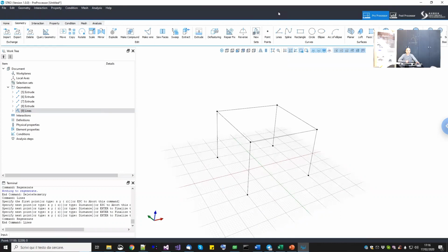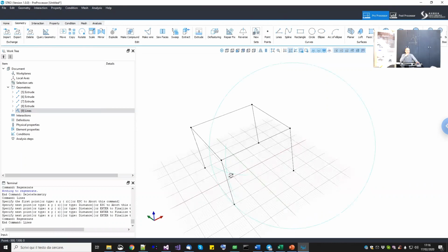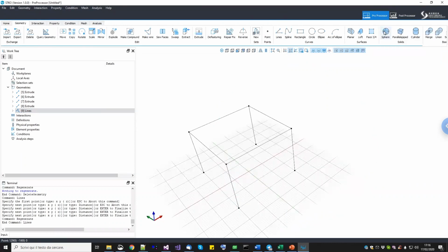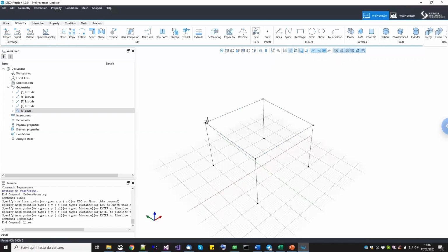Okay, sorry. Perfect. As I told you, in this example we are going to model everything in continuity. Later on, we will add discontinuity at the nodes to create the beam column joints. So if I want to merge all these geometries into a single one, they are all edges, so I can use the make wire command.